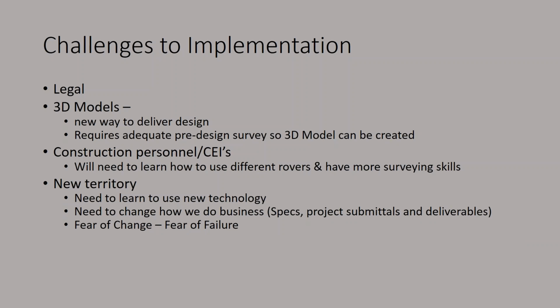I know overbuild's a big one. I want to see some of the overruns go away on that. We don't have enough accurate survey of the existing condition to then say, okay, you need this much overbuild on an asphalt project to bring it back to where the slopes really need to be. And so that gets overrun a lot, and that gets pretty expensive on some jobs.